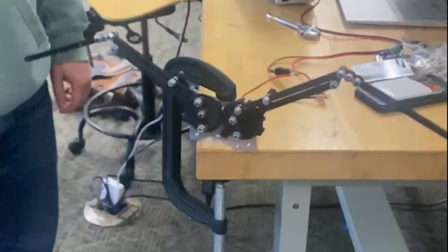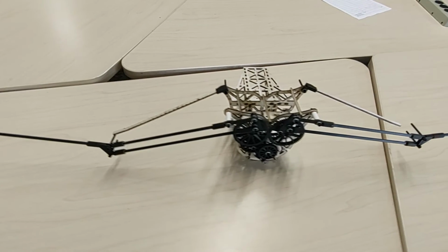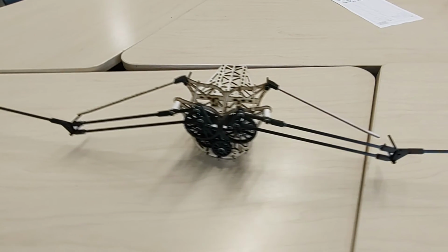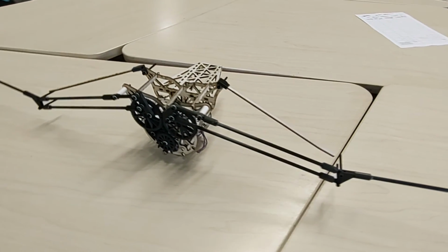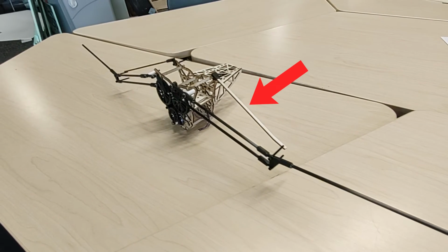However, the other challenge associated with the wing linkages was to determine what material to make them out of. Like the airfoils, they needed to be lightweight but also able to withstand impacts. It was for this reason that we decided to use carbon fiber rods, with balsa supporting rods mounted on the back of the wing for extra stability.